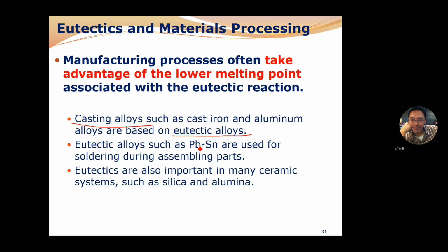For casting, we have to control the viscosity of the liquid metal, to control the liquid phase. If we choose a different composition, a hypo or hyper eutectic composition, what's going to happen in the casting process? The liquid may not flow through the pattern, the whole mold that you design.